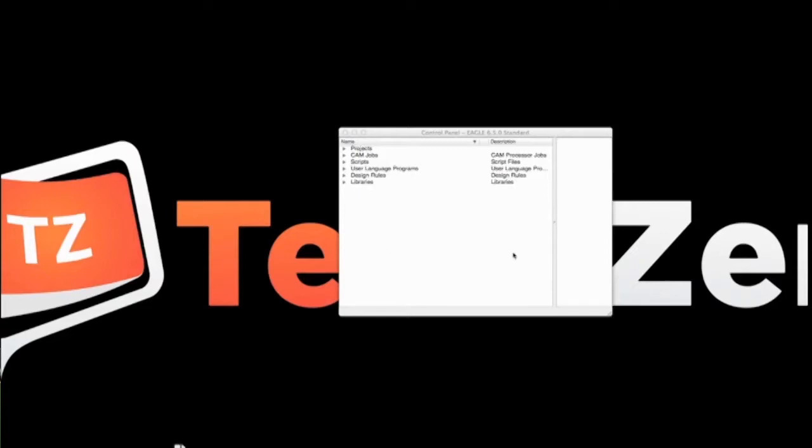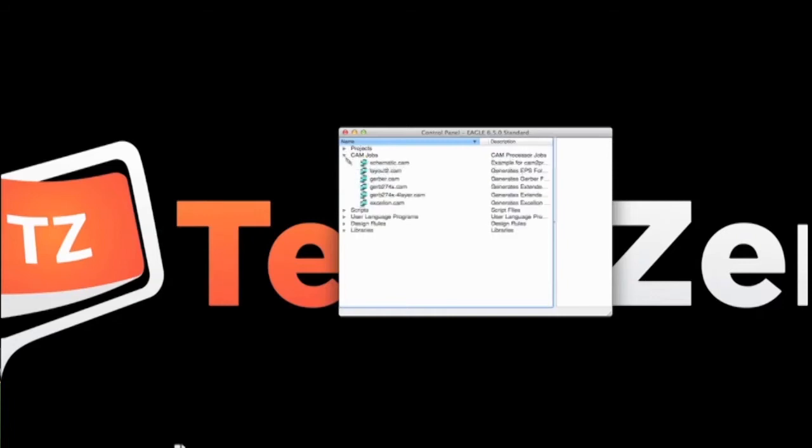All right, so what you see here is what you see in Eagle when you first start. It looks a little bit daunting because it doesn't really tell you what to do. But this is what the control panel looks like. And if you have projects created, you can come in here and you can see projects. I don't generally do them under projects. I just do them as individual files and put them in folders. I've never really adopted the projects thing. The CAM jobs are what you can use to actually generate your output. Here's a Gerber output. We actually have our own that we created for the company that we use.